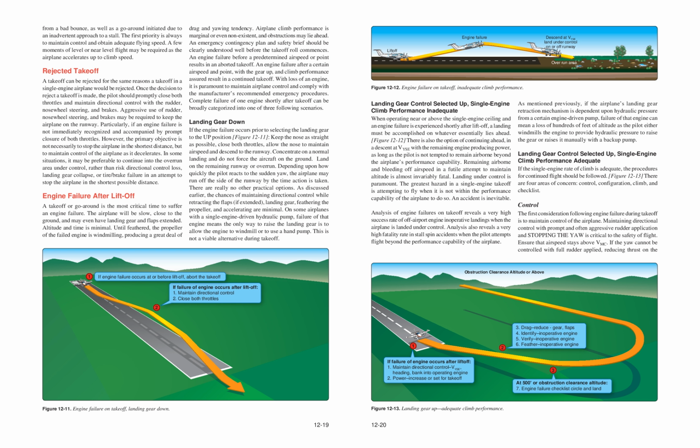Control. The first consideration following engine failure during takeoff is to maintain control of the airplane. Maintaining directional control with prompt and often aggressive rudder application and stopping the yaw is critical to the safety of flight.